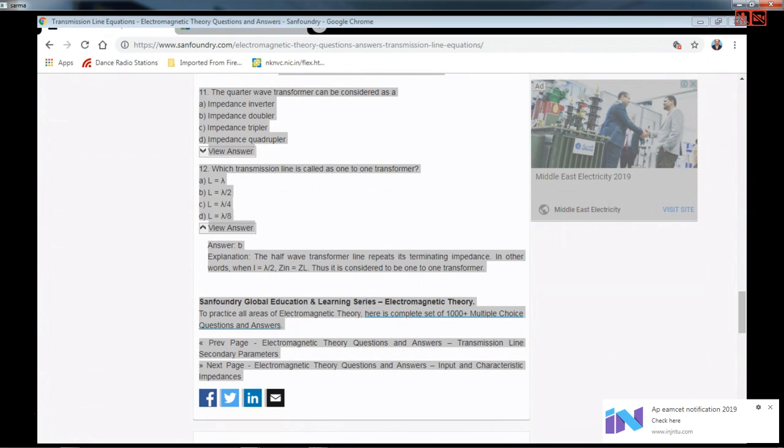There, we are going to talk about the current on a transmission line. The reflection coefficient is also going to be defined in terms of I reflected to I incident, and the voltage reflection coefficient and current reflection coefficient will have a negative sign. Thereby you will have some changes to take care of in the reflection coefficient. However, the VSWR is going to be the same, whether you are considering the voltage ratio or the current ratio, as you can see here.